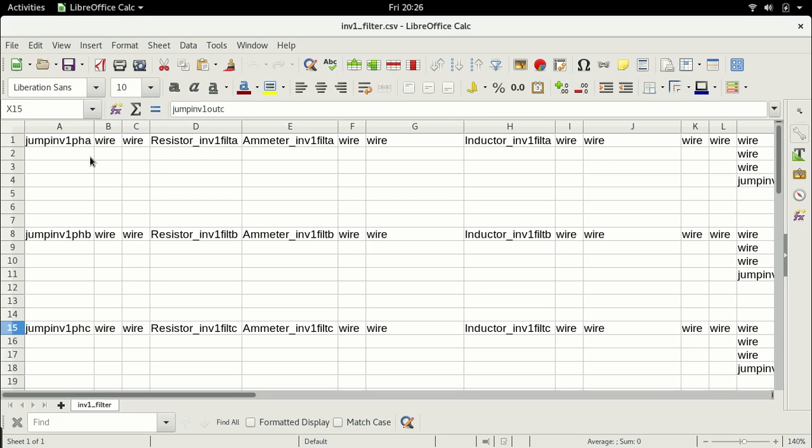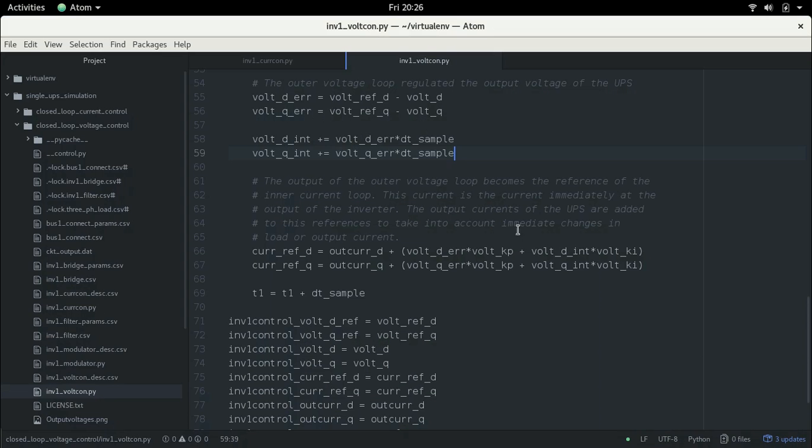Why? Because if you just go back to your regular control theory, if you apply a PI controller to a steady DC value, you will get zero steady state error. If you apply a PI controller to a linear signal or anything else, you will get a steady state error. But if you apply a PI controller to a second order system, you will get an increasing error. It will not track at all. And that's the reason why we cannot apply a PI controller here. What we do, we apply a PI controller, but we don't directly set the modulation index. What we do, we set the references of the current.